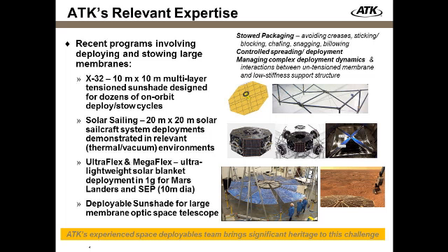Well, we did one of the initial solar sail deployments, and that's a picture of the top view at Plumbrook. So this was 20 meter by 20 meter, about 100 feet across if you look at the diagonal, and deployed that in vacuum and at both the temperature extremes and showed how that would operate there. We are developing Megaflex. Here's a picture of our EDU wing that's basically going to Plumbrook next month. We'll be deploying that in vacuum, and that is 10 meters in diameter. We'll produce about 20 kilowatts per wing and extensible up to a 30 meter diameter, which would create power of about 175 kilowatts.